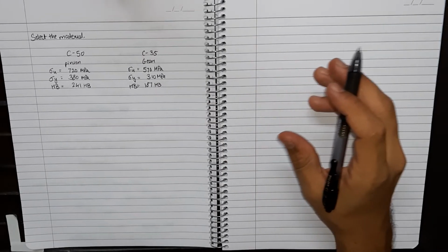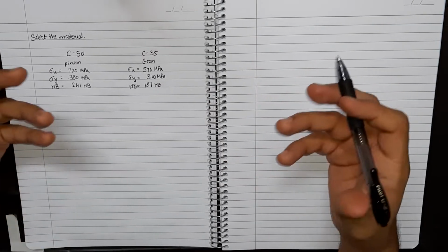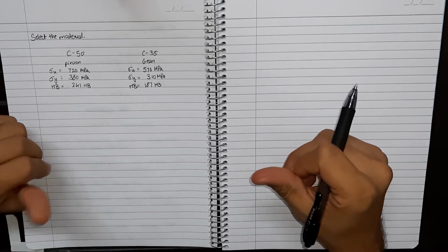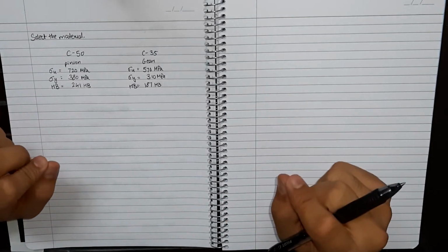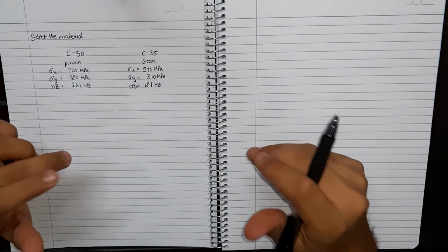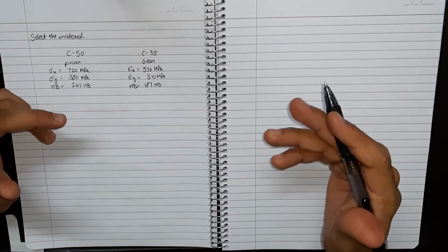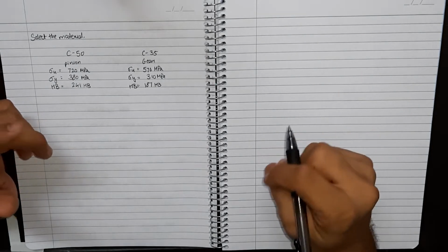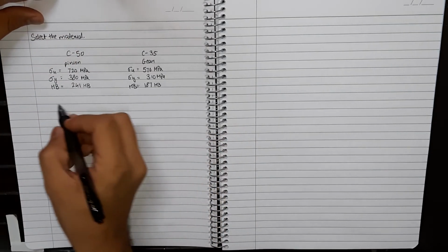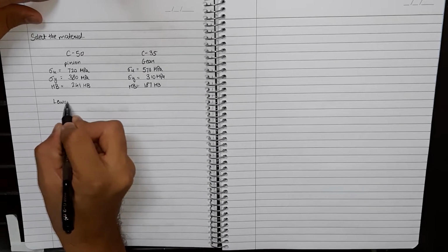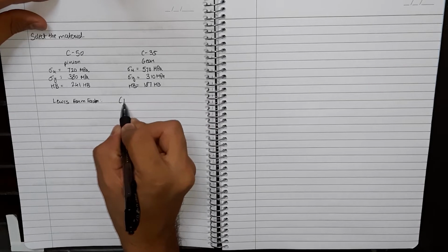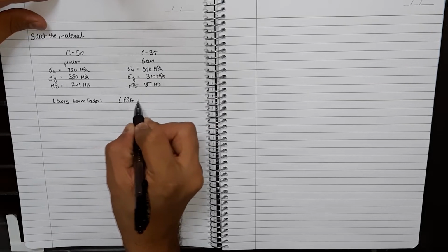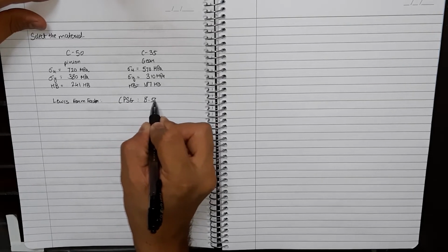So the first task on our hand is to check which element is weaker. Whether the pinion is weaker or the gear is weaker. Generally, it is a notion that the pinion should be the weakest element and we have to design the pinion first, and accordingly we have to find the value for module and the number of teeth for the gear. There is one way to check that using a Lewis form factor. The formula for which is given in the PSG Databook on page number 8.50.